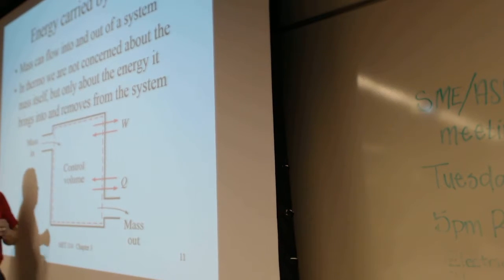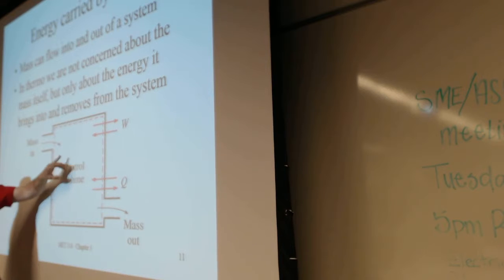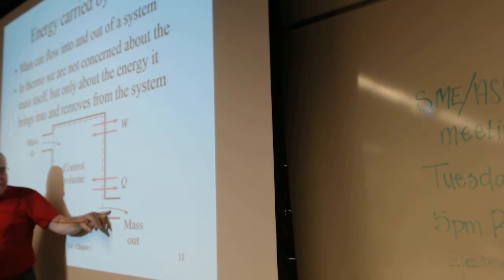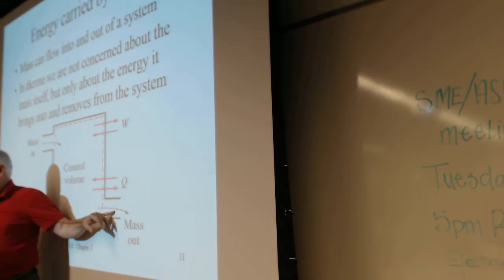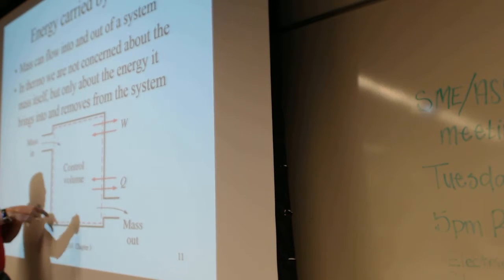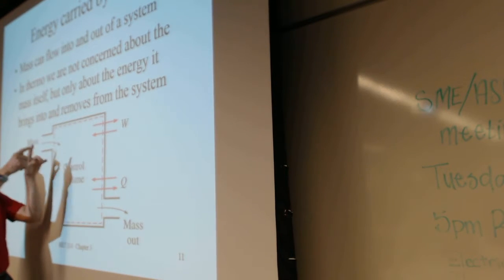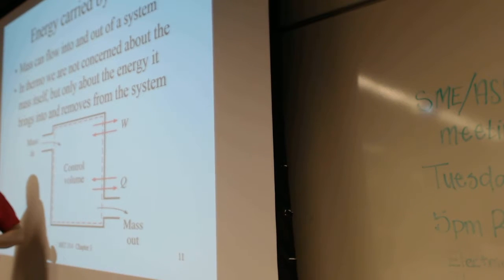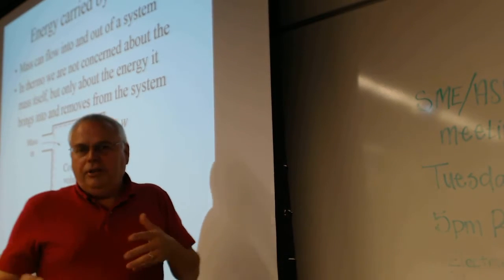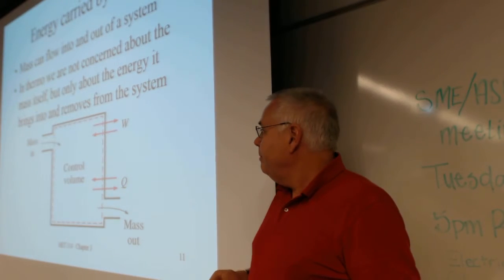Likewise, for refrigeration, this might come in with a certain amount of energy, and now we put work into the compressor. And what comes out is at higher pressure, higher temperature, and that goes to the back of the refrigerator to cool down. But it depends, are we drawing a box around the entire refrigerator or just around the compressor, the steam plant? We can define what it is that our system is. But that's what the first law will be. We'll be looking at work and heat. How does it come in? How does it go out? And we are accountants for that.